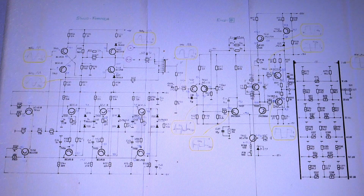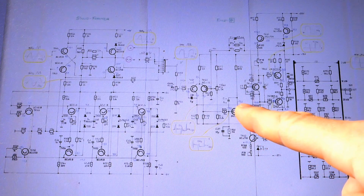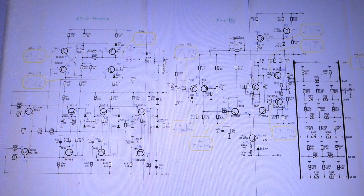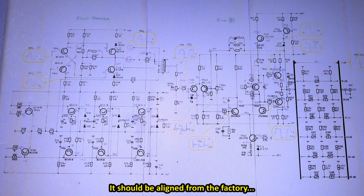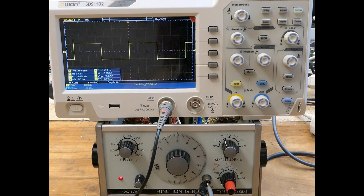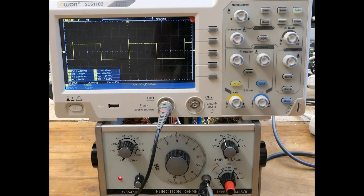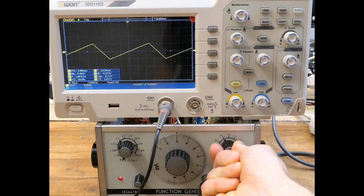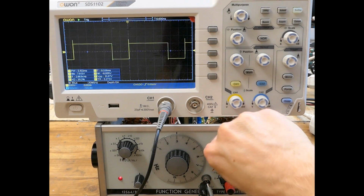Of course, the final amplifier could be somehow aligned for minimum distortion, and the potentiometers could be aligned in this sine wave contraption, looking at a Fourier transformation and minimizing the harmonics, but I think this is already over the top. I managed to adjust it right with the wrong transistor in it, so it's not extremely critical, it seems. And now it's working basically as good as I can imagine this 40 years old thing working.